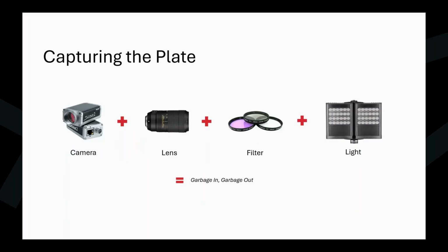This all goes to say, though, that it's not just a lighting emphasis. You need to take into account the entire solution. So you need to have a suitable camera, you need to have a good lens, filters in some cases. So for example, if you're using an infrared bandpass filter, so that you're only looking in black and white through day and night, or as we'll come on to later on in the presentation, if you're looking through things like car windscreens, you need to have a polarizing filter.